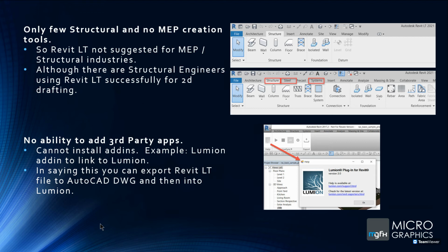There are some materials that don't come through, but you can solve that in a different way using Lumion material sets, by setting and loading those material sets to be more productive applying materials in Lumion.